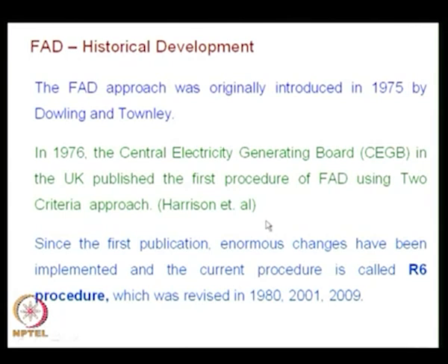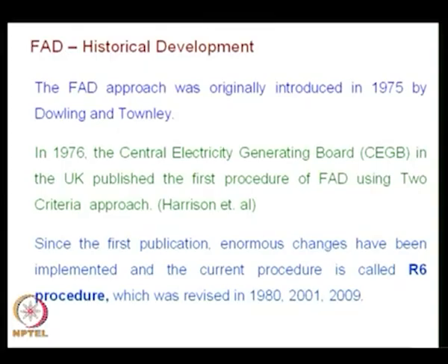So, this FAD approach helps to investigate whether brittle fracture would occur, or plastic collapse would occur, or whether it will be controlled by EPFM concepts. So, this whole spectrum is looked at in this approach, and the basic procedure is as follows.